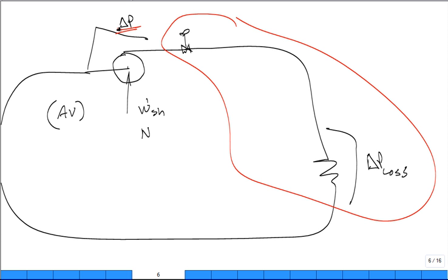You're a devilish little fiend and you continue to crank down that valve, closing it. What does the pressure loss in the system do? Goes up. What does the flow rate, the AV through the system do? Goes down. What does the pressure that the pump has to do? Goes up. You keep cranking down that valve. The game keeps on until guess what happens?